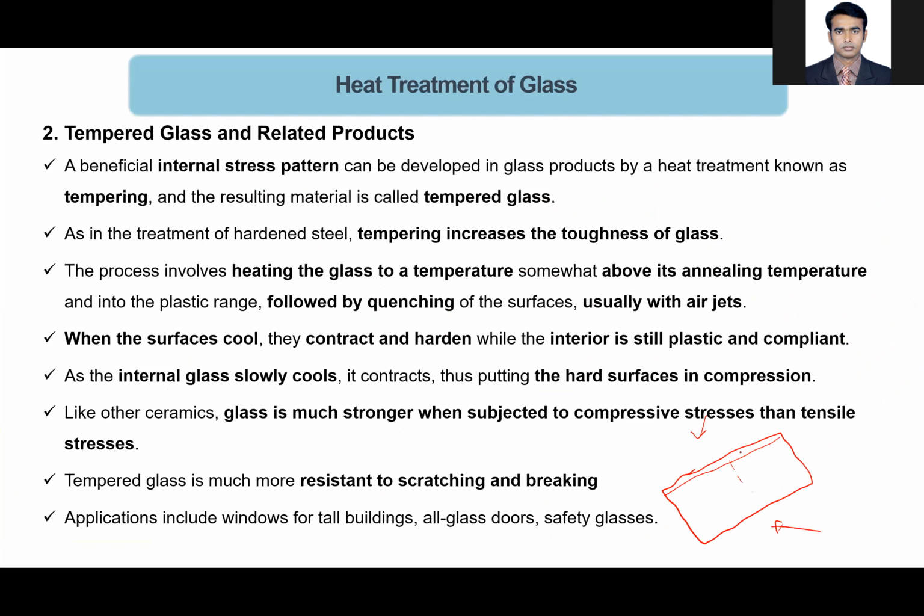At that time, the atoms or molecules on the outside will be more randomly distributed compared to the inside material. That's why the outside surface provides more hardness, and the inside has sufficient time to reorganize and will have less internal stress. That is why the inner core provides the toughness, and it's not like a certain layer.